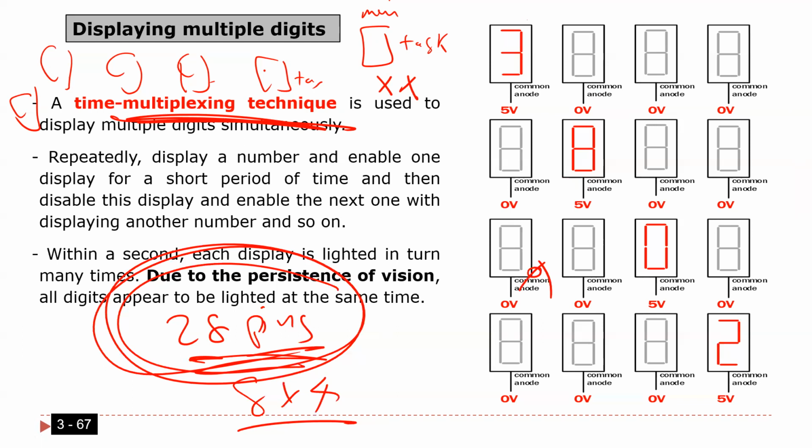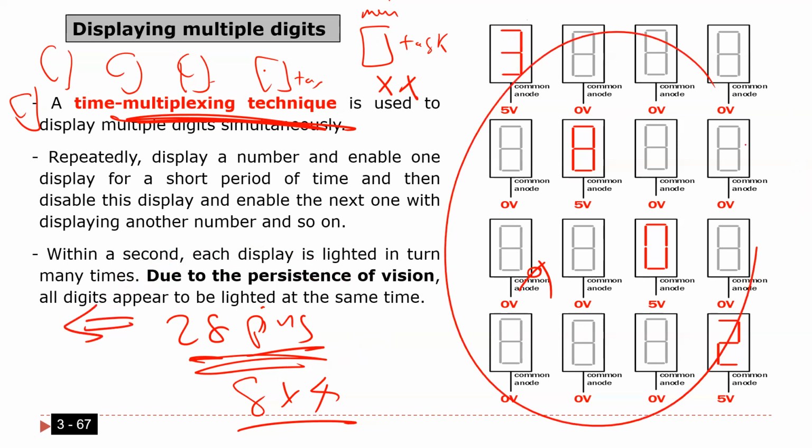Microcontrollers usually don't have a lot of pins. Even if you have a lot of pins, you still want to maximize the use of them, because if you want to connect too many things, you got what I'm saying? But anyway, last time I showed you that, because of the time multiplexing and also because of using a shift register, I'm going to use only three pins. Very interesting.